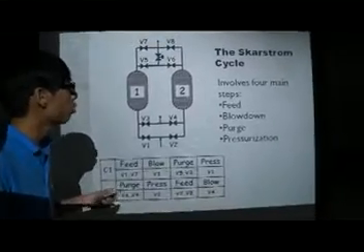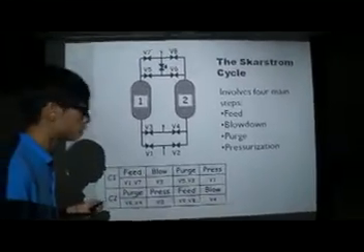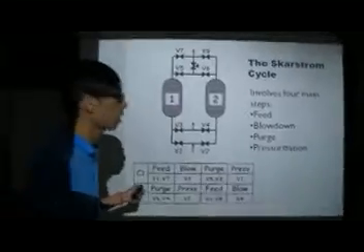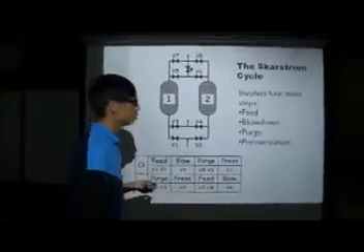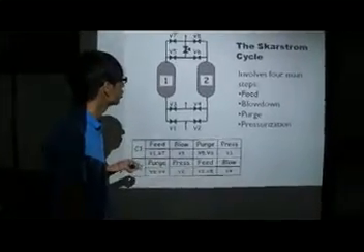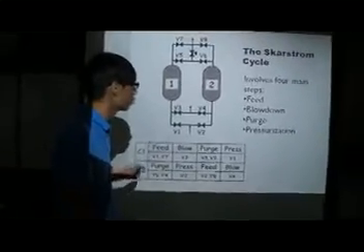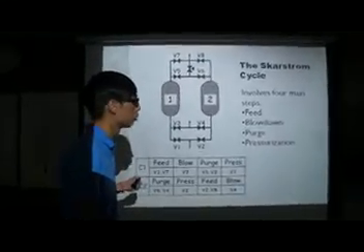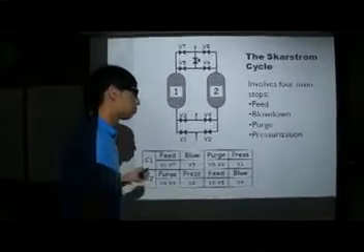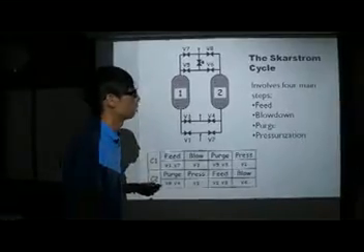The blowdown step is where the feed to the first column is stopped and is rerouted to the next column for adsorption. By doing so, we can open valves V5 and V3 so that the gas trapped inside the adsorption column is released via blowdown. The next step is the purge step.